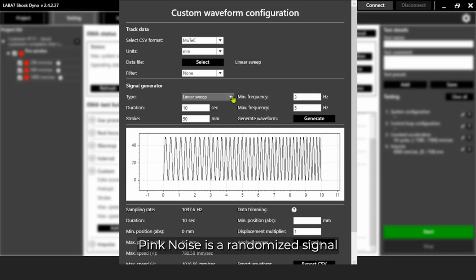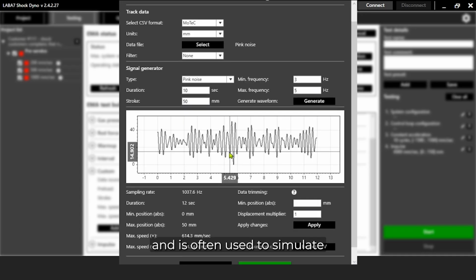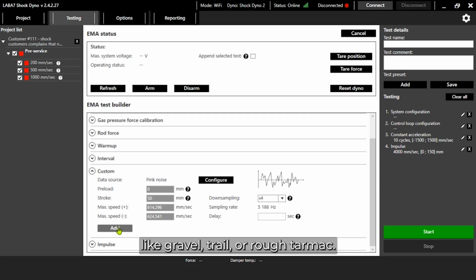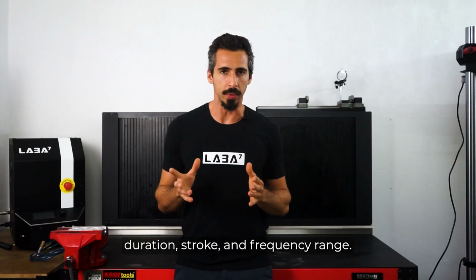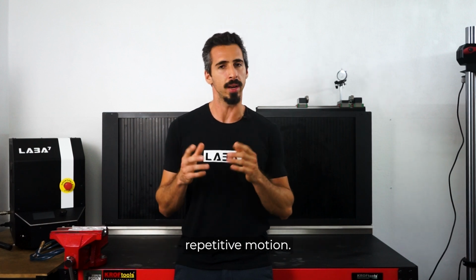Pink noise is a randomized signal that mimics real terrain input. It distributes energy more naturally across frequencies and is often used to simulate unpredictable environments like gravel, trail, or rough tarmac. You can define test duration, stroke, and frequency range. These tests help reveal behaviors that wouldn't appear under clean repetitive motion.